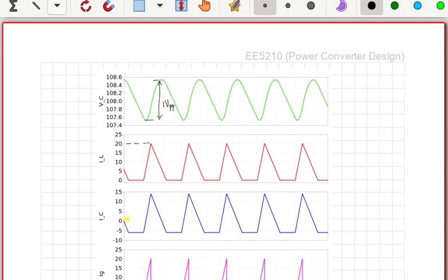And again, you can look at the capacitor current. So if I may draw the zero crossing, this is the portion where the capacitor current crosses zero, and therefore if I now draw a perpendicular from this point, you find that the perpendicular meets exactly at the peak values of the capacitor voltage.